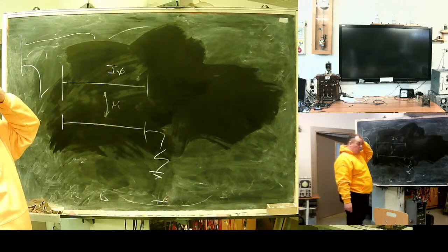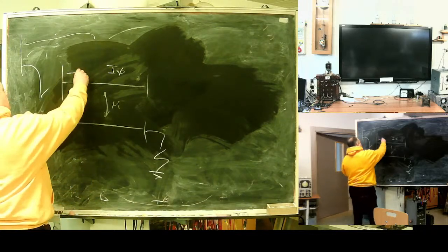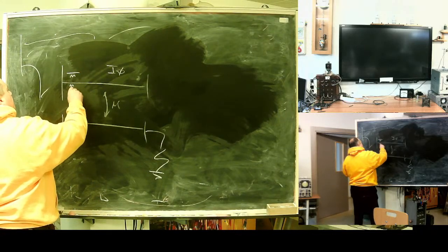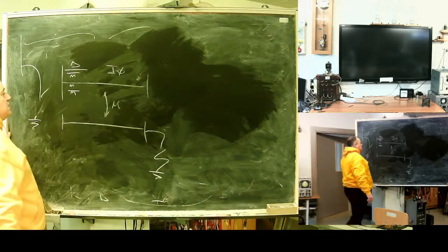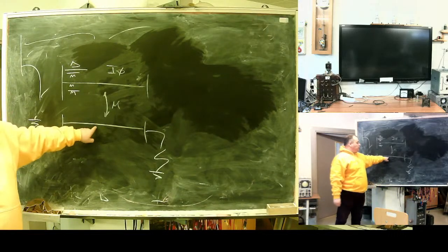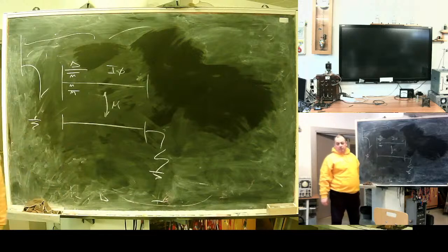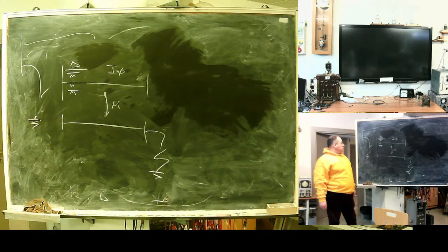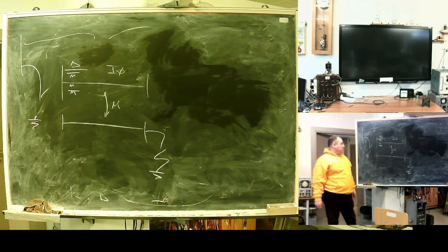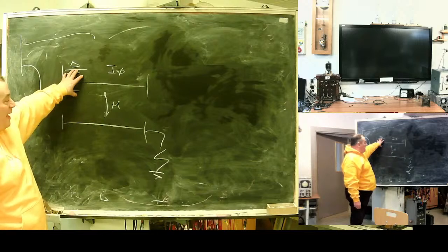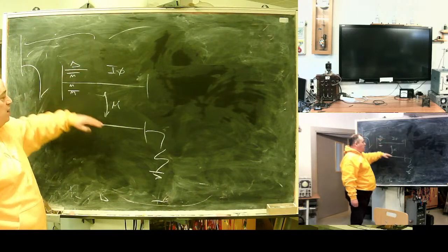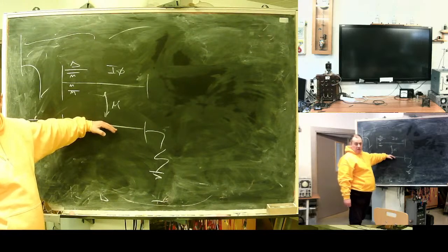If lines are very close, then it can be a problem. Delta connected transformers prevent influence from magnetic coupling. Usually it's done differently. It's done by controlling zero sequence current of the parallel line, but this one is exotic, but it can be. Here we have delta connection to make protection of this line immune to faults on the parallel line.